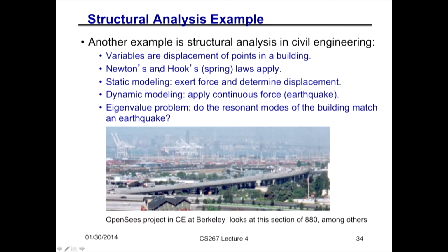So what are the rules that govern how they interact with one another? Well, it's Newton's laws, F equals ma, but also Hooke's law, which is just the spring constant, right? If something moves, then what's the force? It's proportional to the spring constant times the displacement. So you write down all those laws for everybody connected to everybody else. And so what are the 3 questions you could ask once you write down all those laws? The simplest one is called static modeling. You exert a particular force and you ask, how far does everything move? That's just solving a big sparse system of linear equations.